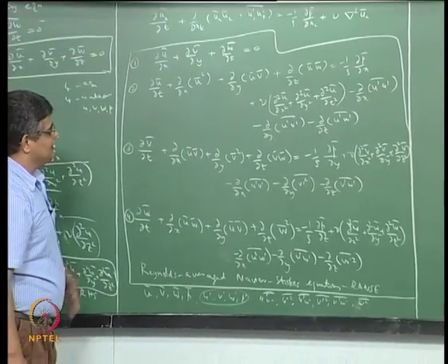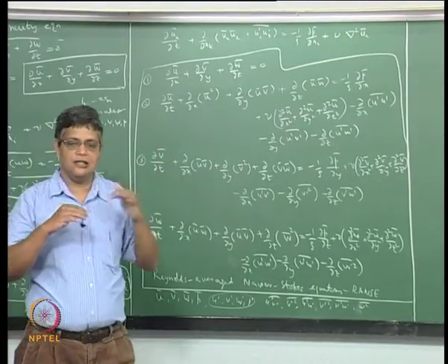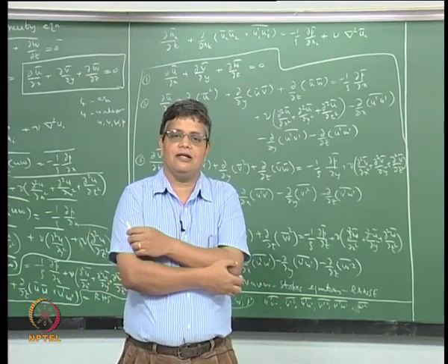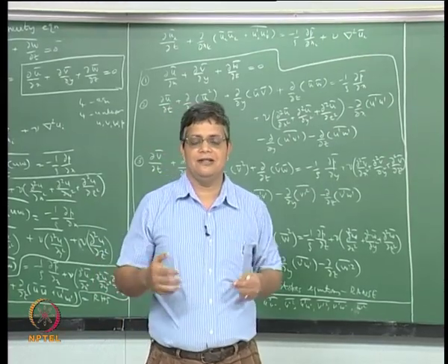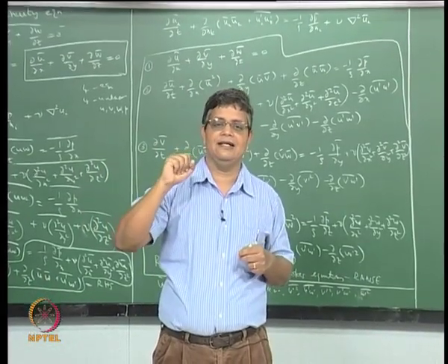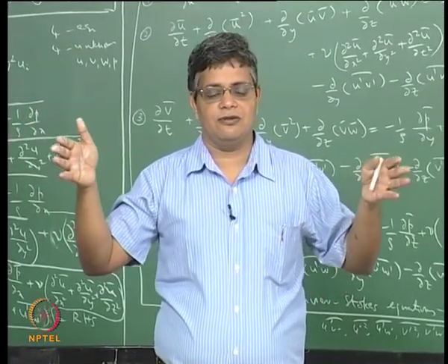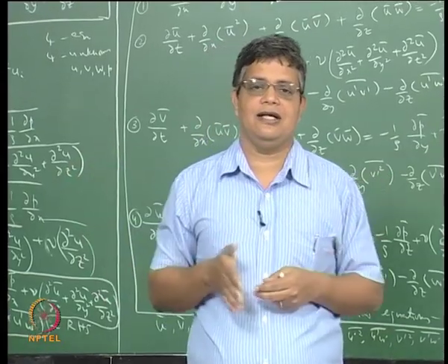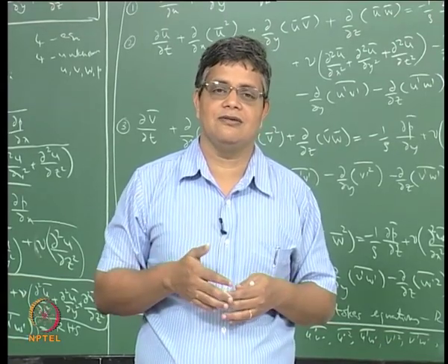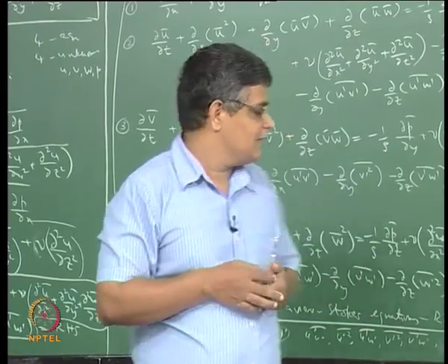If you do that, then let us take the case of fully developed turbulent flow between 2 infinitely long plates. It is like the Couette flow kind of assumption, Couette flow with a pressure gradient. So you have 2 infinitely long plates which are separated by a constant distance, and you have steady inflow, and therefore the flow is driven by a constant pressure gradient, even though it is turbulent flow, with the idea of steadiness.